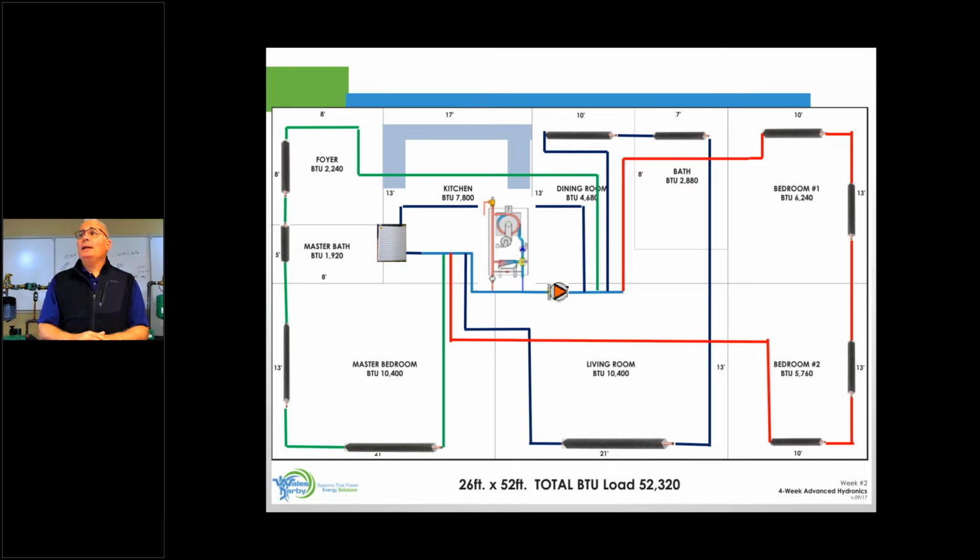I also just want to point out the way the boiler is piped as primary, secondary. And you can see we have the circulator on the supply side. We are pumping away from the boiler. Yeah, I know the expansion tank's not in there and all the other fill valves and stuff. Neat and clean, just so everybody can see what we're doing. But we do want to pump away. We do want to add positive pressure to the system, which we will go into detail going forward in our next classes.